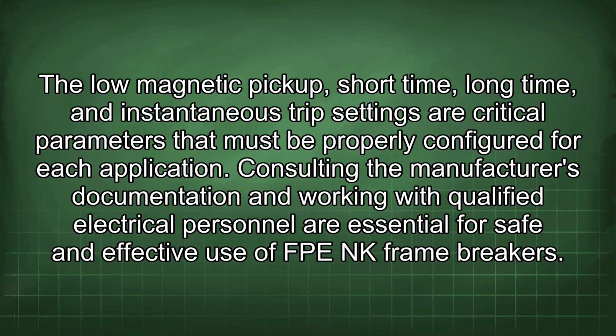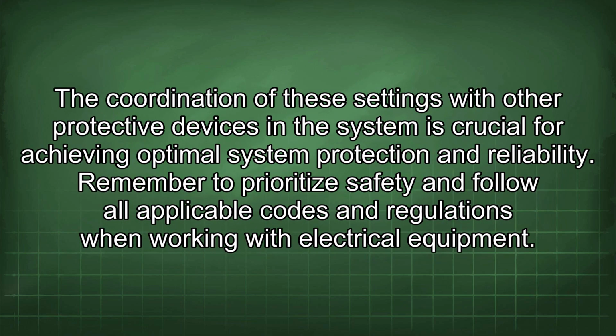The low magnetic pickup, short time, long time, and instantaneous trip settings are critical parameters that must be properly configured for each application. Consulting the manufacturer's documentation and working with qualified electrical personnel are essential for safe and effective use of FPE NK frame breakers. The coordination of these settings with other protective devices in the system is crucial for achieving optimal system protection and reliability. Remember to prioritize safety and follow all applicable codes and regulations when working with electrical equipment.